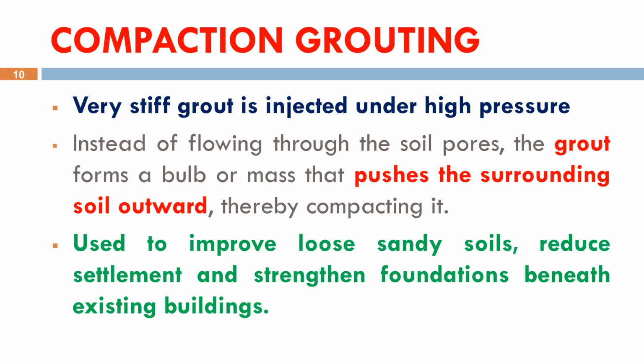Compaction grouting is commonly used beneath existing buildings, bridge foundations, and industrial structures to reduce settlement and strengthen loose sandy soils. One major advantage is that it improves the ground without the need to excavate or disturb the existing structure.